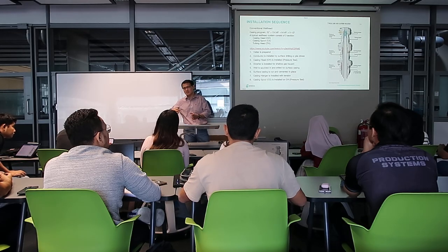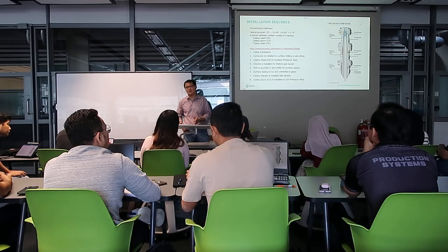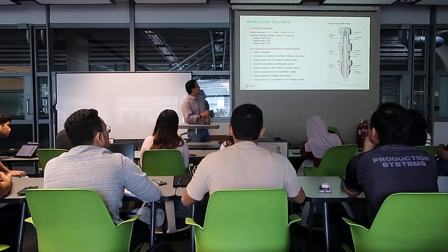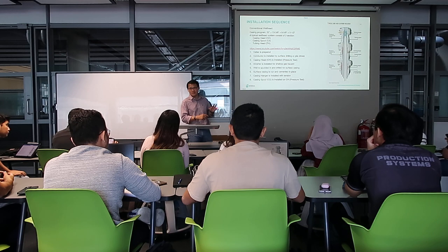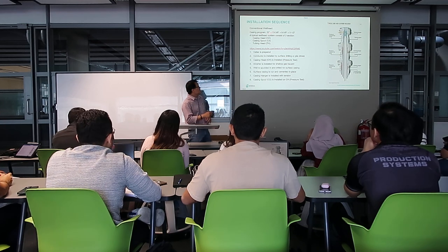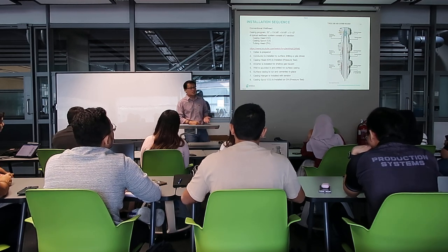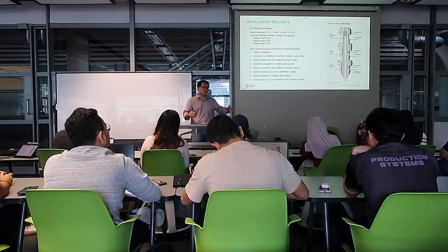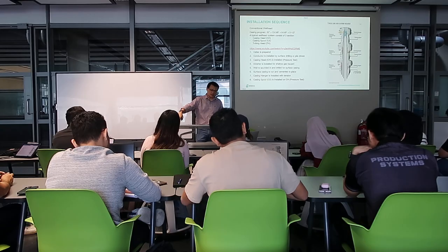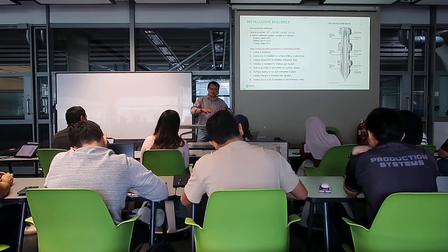So then you start seeing some slightly different things. So this is a typical casing program, 20. So they have three spools, three housings here, and then this is a casing program just for example. So if we are using a 20-inch conductor, so basically we prepare a cellar. So what the cellar means is, actually, for onshore wells, they will excavate the soil. They will make a cellar.